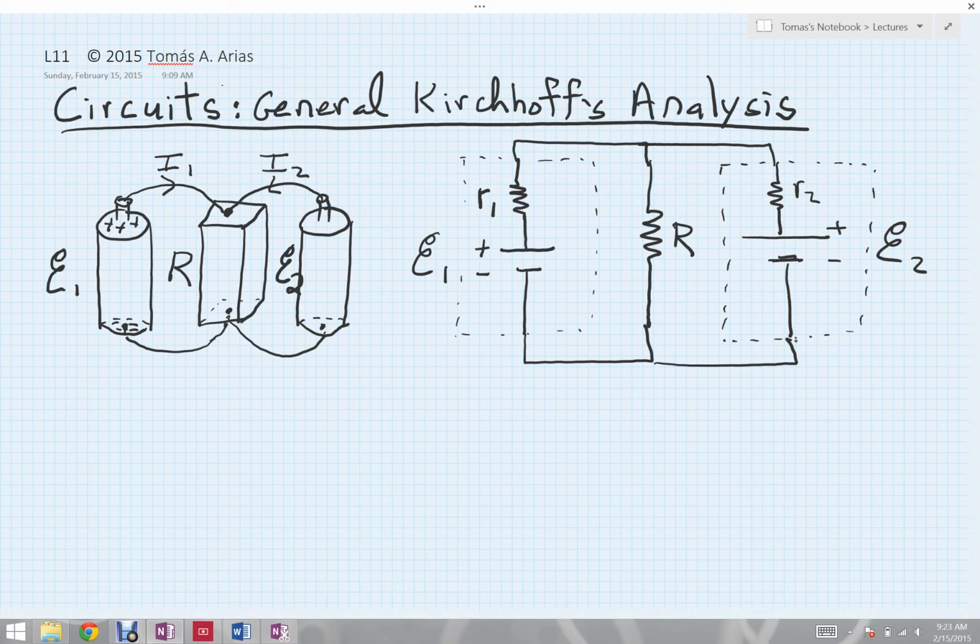Now, you'll notice that although I have a number of resistors here, I can't lump them together as any kind of series or parallel combination. It just is not amenable to that kind of reduction. If you look at first, you might think, well, wait a minute, little r1 and big R certainly appear to be in series with one another, but there's this interesting junction up here that connects things to r2. And in fact, if you remember our definition of a series combination of circuit elements that our whole derivation depended on, there were two things.